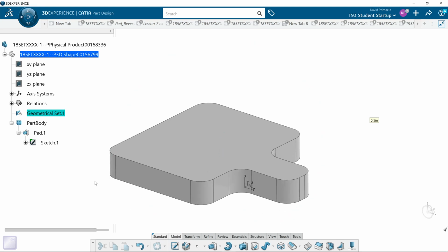Now, we talked about the radius being positive and negative, all depending on what direction I'm going. So if my cutter's here and I'm going in this direction, am I going positive or negative? Positive. Okay? This face and this face, assuming it's 9/16. I'm going into this radius at a 9/16 radius, positive or negative? Negative. This one's positive and this one's negative. And this one is. Positive. Yeah. So we have negative and positive radiuses.